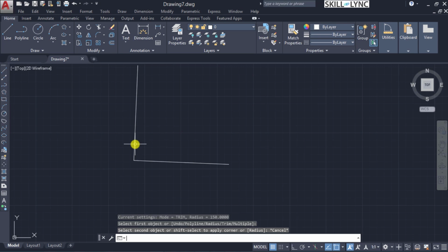And in terms of layers that we are speaking about, if the objects of fillet are on the same layer, then the fillet line will be on that same layer. So it means that this is going to get retained in the same layer of view that you are going to use. So next, we can also fillet line segments in a polyline that are either continuous or separated by an individual line segment, and also that converge within the drawing limits. So in those cases we can still do it.